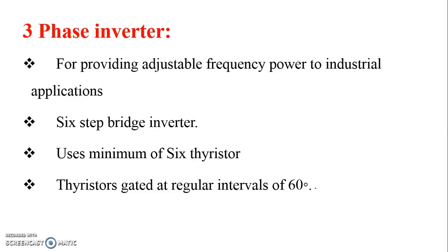The three-phase inverter is also called a six-step bridge inverter because it uses a minimum of 6 thyristors. Each thyristor is turned on or gated at a regular interval of 60 degrees.